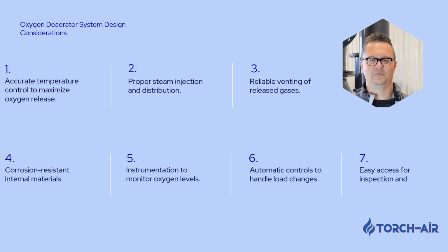Oxygen deaerator system design considerations. When I design a complete oxygen deaerator system, I always include, first, accurate temperature control to maximize oxygen release. Second, proper steam injection and distribution. Third, reliable venting of released gases. Fourth, corrosion-resistant internal materials. Fifth, instrumentation to monitor oxygen levels. Sixth, automatic controls to handle load changes. Seventh, easy access for inspection and maintenance. If any of these are missing, corrosion will find a way back in.